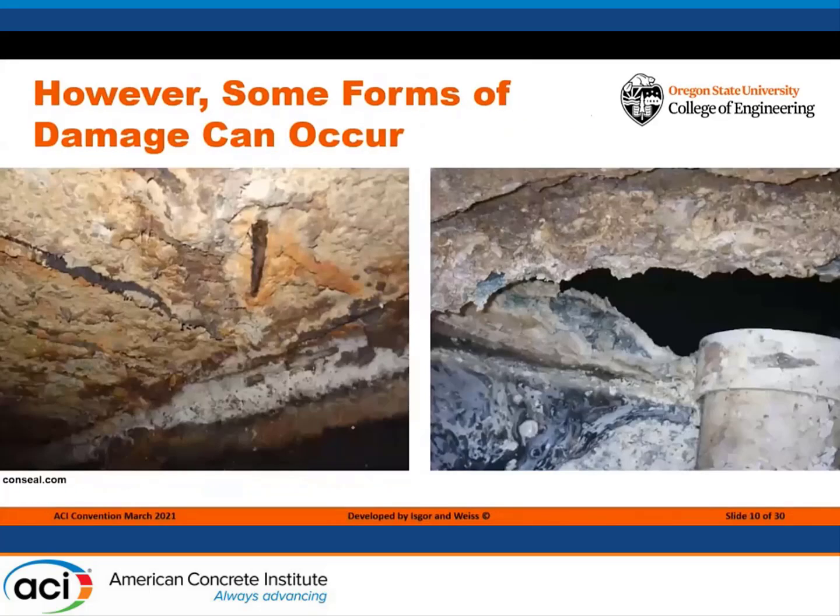However, as I say that our concrete has been durable, we start to see that some of our concrete infrastructure in the sewer infrastructure can start to decay and degrade like we see in these pictures. This is really the decay that's consistent with microbial corrosion. If we look at how much decay happens annually in a well-functioning system, this could be fractions of a millimeter every year.